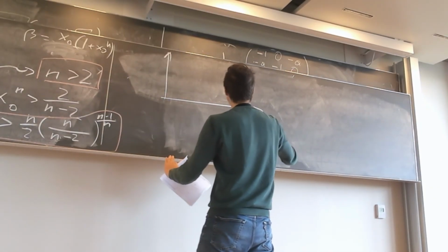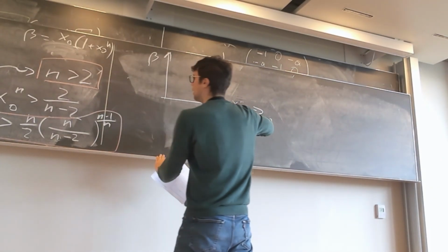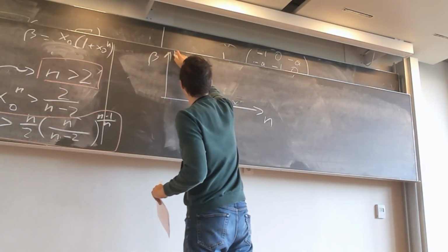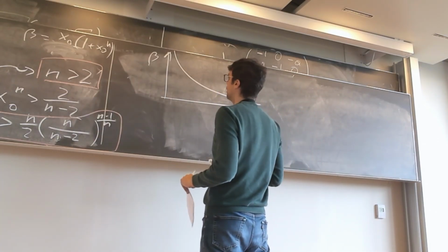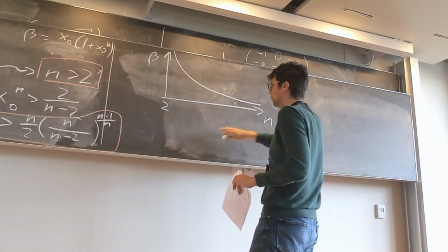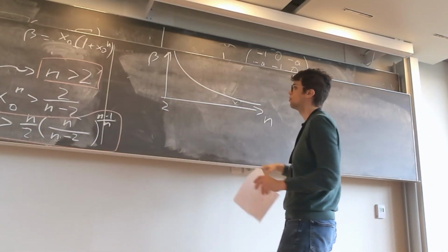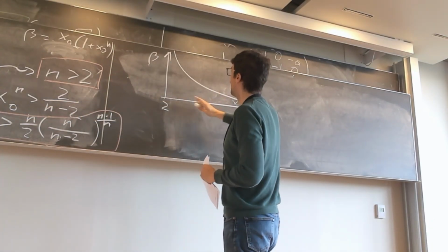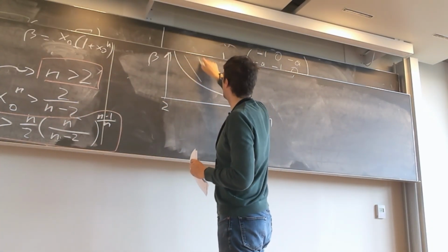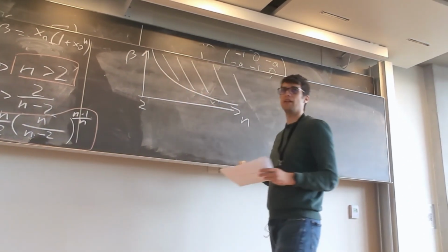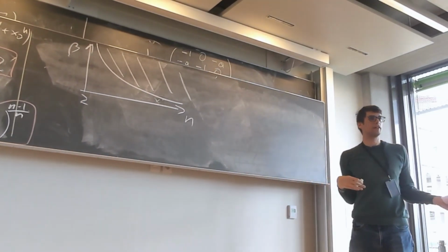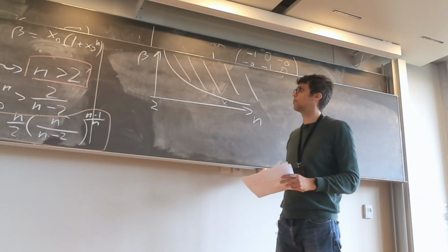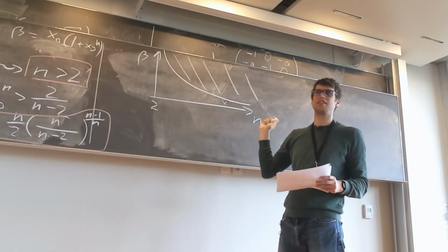If you look at the n-beta plane here, it turns out that this function is just a decreasing function in n. And of course it starts only at 2. The possible range of n starts at 2. But if you're above it, there is a given beta that is sufficient. And this is a decreasing function. That means that if you have an even higher n, you can get away with a bit lower beta. So here would be the possibility range of oscillations for our system. High n, high beta, but you can trade them against each other a bit.